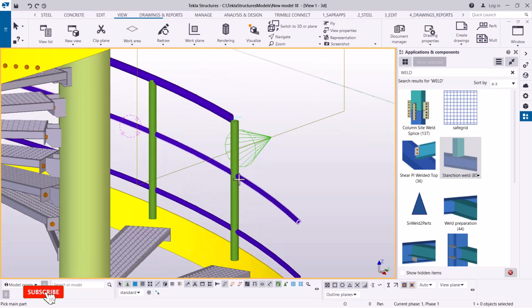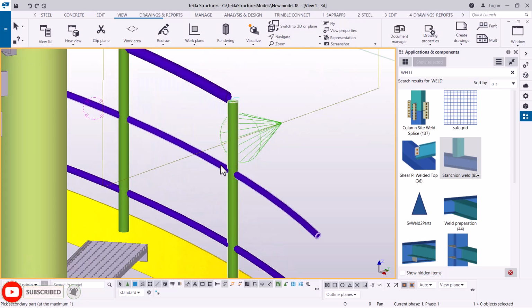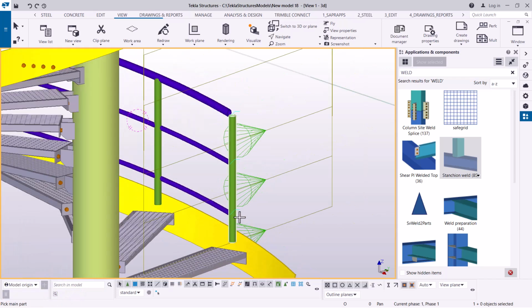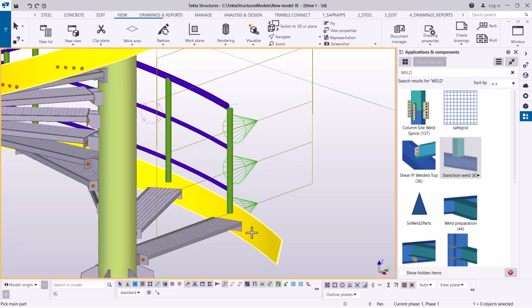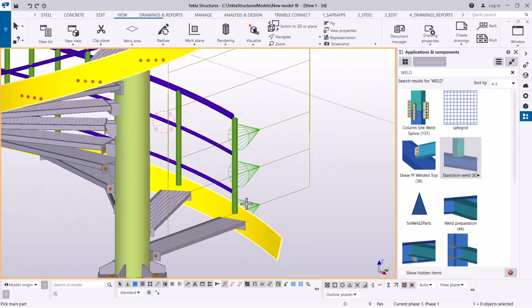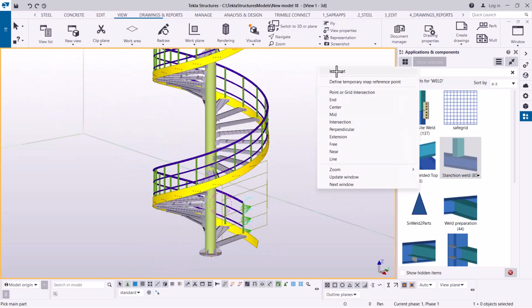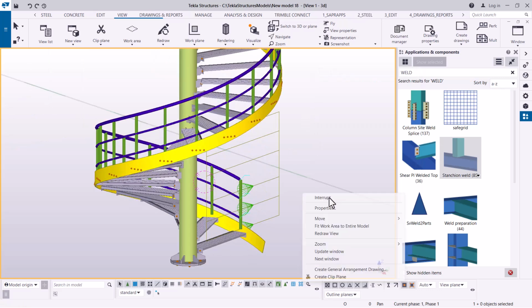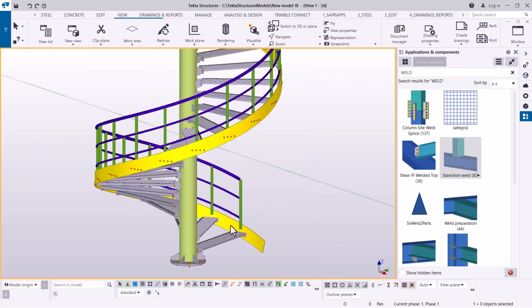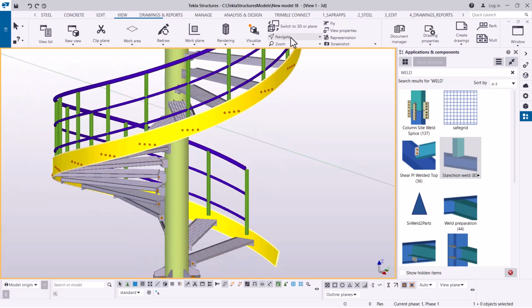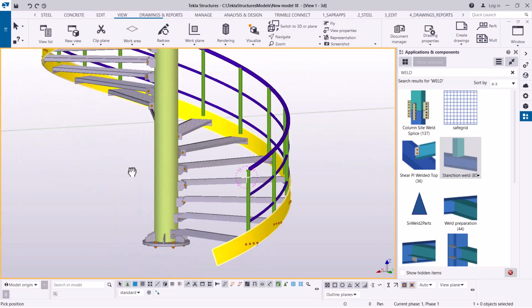It's not missing any part of that. So I'll weld this to this. Let's see, and we'll weld this to that, and that has trimmed that off. So we have that member in that section. So cutting off this part of the stringer is not an issue. There's another way you can trim: you can extend this member to join with the handrail post in a better way.